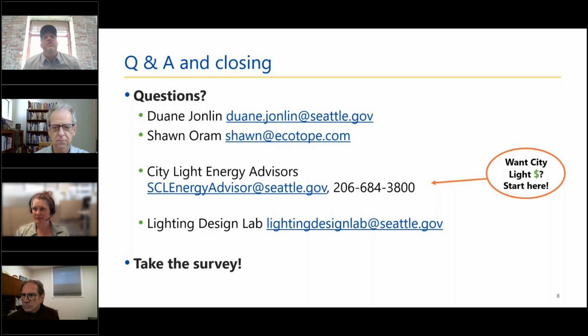Good question. So the city water in Seattle, most of it has surface reservoirs, and those will heat up to 70 degrees by September. The coldest water in Seattle happens in March when all the ice is melting, and so the groundwater is super cold. But the variation is about 10 degrees on 52. So 52 minus 5 plus 5, but then the surface reservoirs take it all the way up to 70 in September. What I would recommend, 50 has been working just fine for us. If you're close on something, then drop it to 45 for local climates. In California, 50 is sort of the low end down there. They're a little bit further south, more sun.